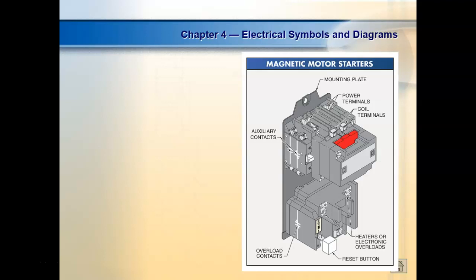So all the current that goes through the motor runs through the overloads. And the overloads are there to determine if the motor does not start or if it stalls. Because your overcurrent protection devices have to be rated to let the motor start, right? You understand that? And if it lets the motor start and the motor stalls, then your circuit breakers and your fuses are not going to trip out. So we have to have a circuit that detects if the motor does not start, right? We talked about that, right? And these are your overloads.